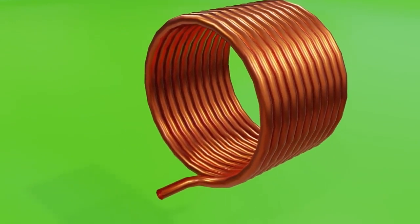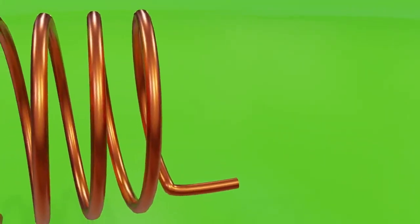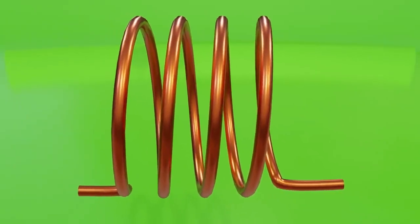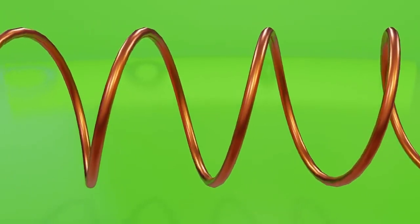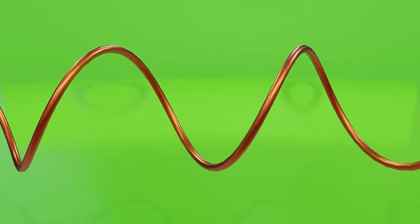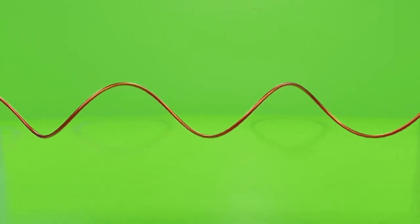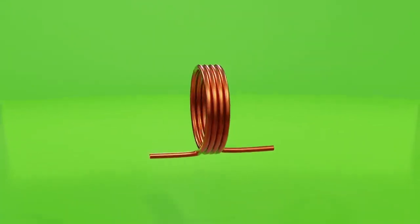be generated. The second parameter is the length of the inductor, because in order for the magnetic fields of each coil to add up effectively, they must be as close as possible. In fact, remember this relationship. Try to think of the opposite case. If the length were extremely long, we would practically end up with a wire, which we know does not act as an inductor. Therefore, the shorter the length, or the more compact the inductor, the greater the inductance.